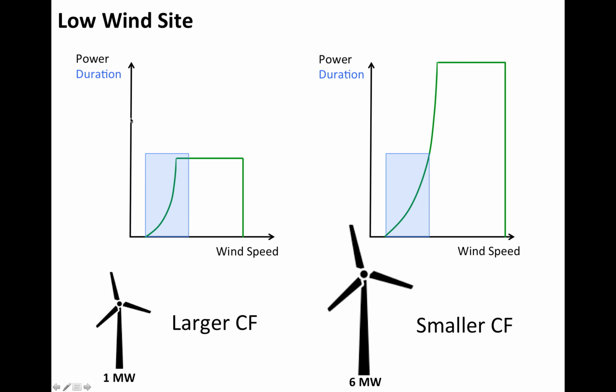If you have confusion about this kind of graph, the annual energy production is just the actual running power of the wind turbine multiplied by the duration of the wind at a certain wind speed, right? So this vertical bar of the wind histogram basically just tells you the duration.